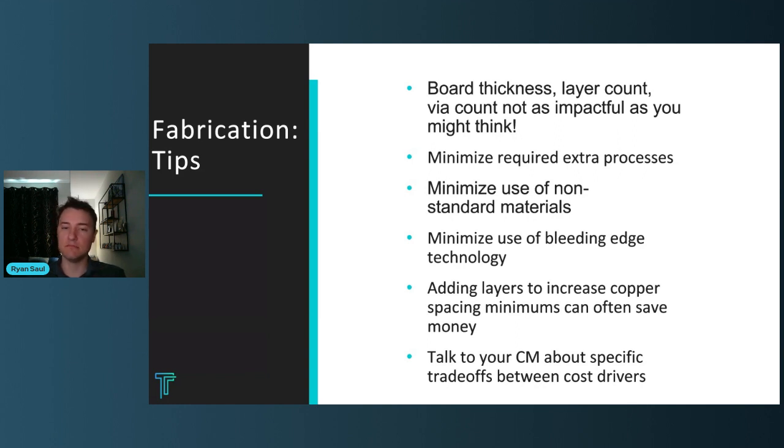I know, obviously, you can't always do that if you're designing a very complicated board. But even within a sequential lamination build, reducing the number of sequential laminations is going to dramatically drive your cost down. Meaning that if you only have 1 buried drill pair and it's a 2 lamination board, that's going to be much, much less expensive. There's going to be less quality risk, and it's going to build faster than a 3 lamination cycle board. So I highly recommend avoiding sequential lamination.